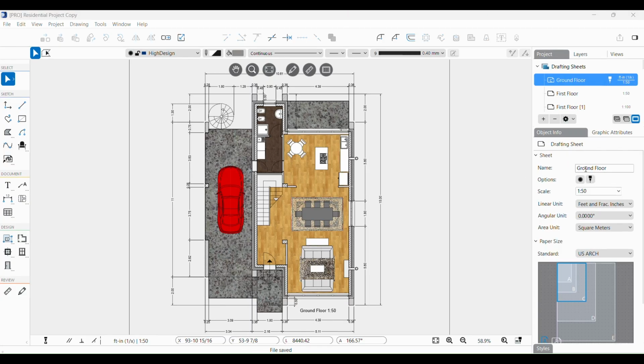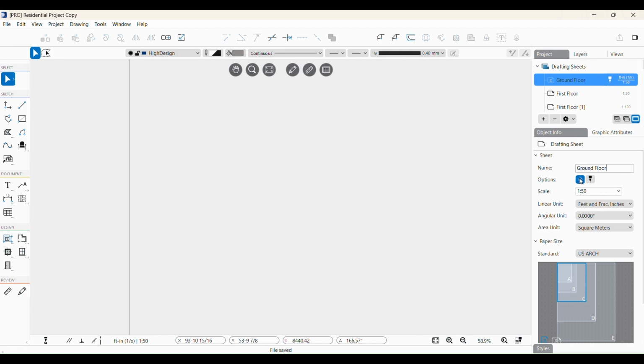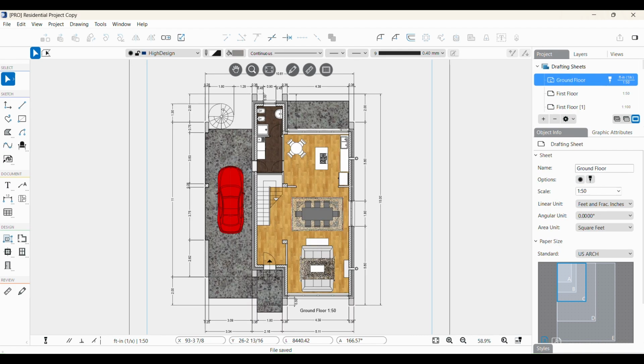Drafting Sheets properties are: Name. You can enter any sheet name without particular restrictions. Visibility. A drafting sheet can be visible or hidden. Hidden sheets are not computed in the general drawing bounds and do not intercept the snap options. Click the icon to change the visibility. Write protection. This option locks the sheet. Objects on a locked sheet cannot be selected and modified.